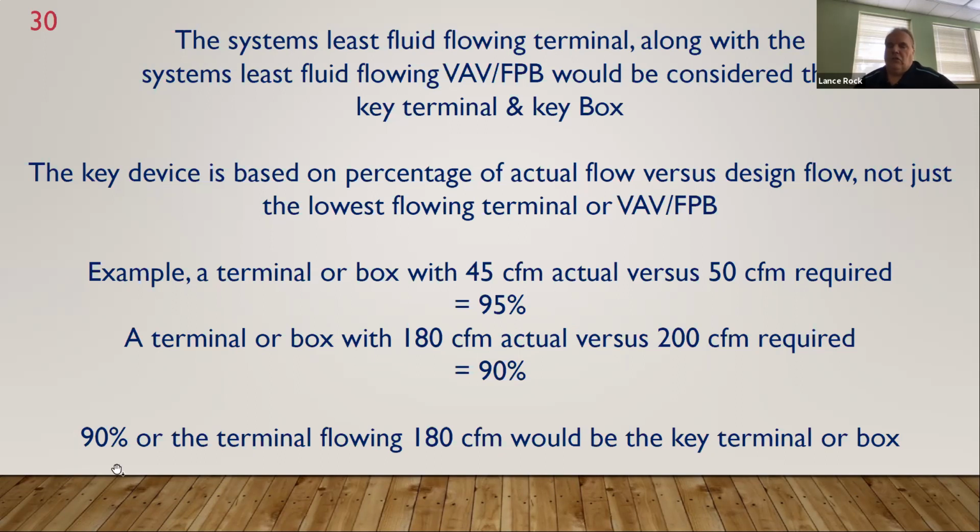Okay, K-factors could be used on terminal devices, but because you said BAS, building automation system, I'm going to assume you mean a VAV system. The K-factors are to be found by the balancer, and that could be the building engineer with a flow hood himself or a pitot tube. The K-factor could be either the square root or a simple division K-factor. It's dependent on the software being used, Johnson Controls, Siemens, and how the K-factors are actually changed. They're pretty intuitive now. The box thinks it's flowing 500 CFM, and the balancer reads an actual of 420. There are some programs where you can enter 420 actual, and it will automatically change the K-factor.